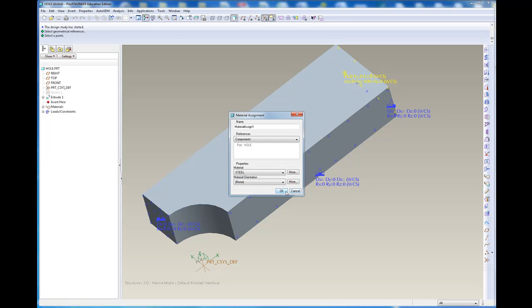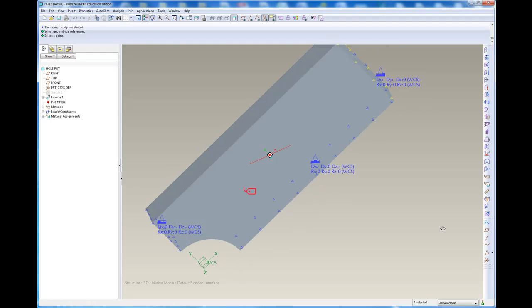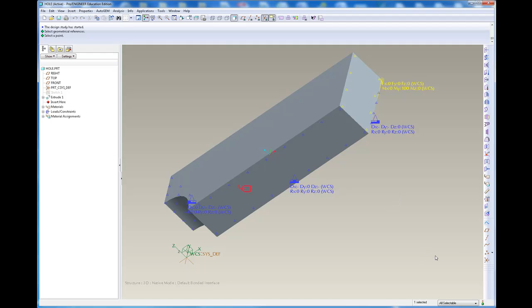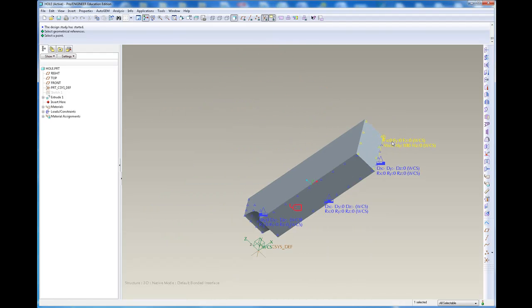Steel, okay. And now I do have materials in this part. And I think I'm ready to run, and I think this thing will run. Let's look, though, very quickly at the notation of this load. It shows a double-headed arrow, it's hard to see, showing a moment of 100 in the y direction, total at that point caused by loads on this surface. That is what it means.